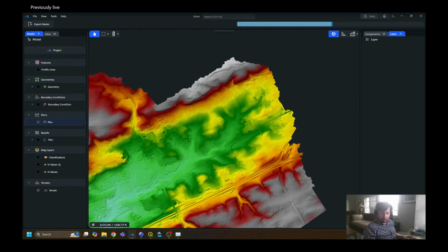Let's see. Why did you choose the diffusive wave equation set? I don't think you have much control over what solver you use in HEC-RAS 2025. When I look at their roadmap, maybe at the end of it, they'll give you control over what solver you can use. When I do modeling in SWMM, I have a lot more control over what solver I use. I'm not sure they call it an explicit solver, and I think that simplifies the equations a bit, but it makes it run much faster, so it's a pretty nice compromise.